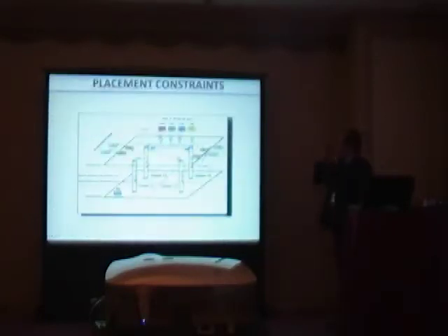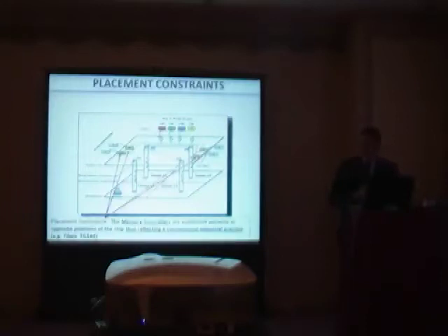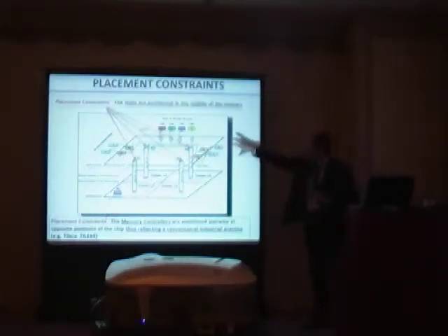So, as I said before, placement constraints are certainly the key contribution to this work. The first placement constraint lies in the position of memory controllers. Memory controllers, in fact, are positioned pairwise at the opposite extremes of the optical layer, thus reflecting a common industrial practice. We think about Tilera TILE64. Instead, hubs are located along a square in the middle of each cluster.